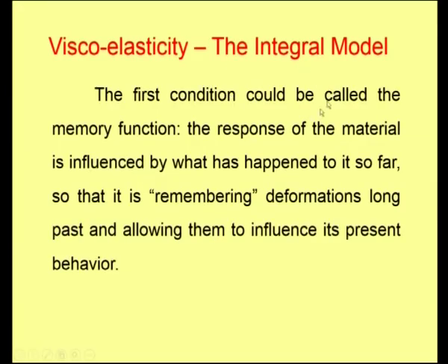The first condition could be called the memory function. The response of the material is influenced by what has happened to it so far, that is, remembering the deformations it has already been subjected to, and allowing them to influence its present behavior. Whatever deformation the material was subjected to already will have an effect on the present deformation, which is due to the applied stress now.